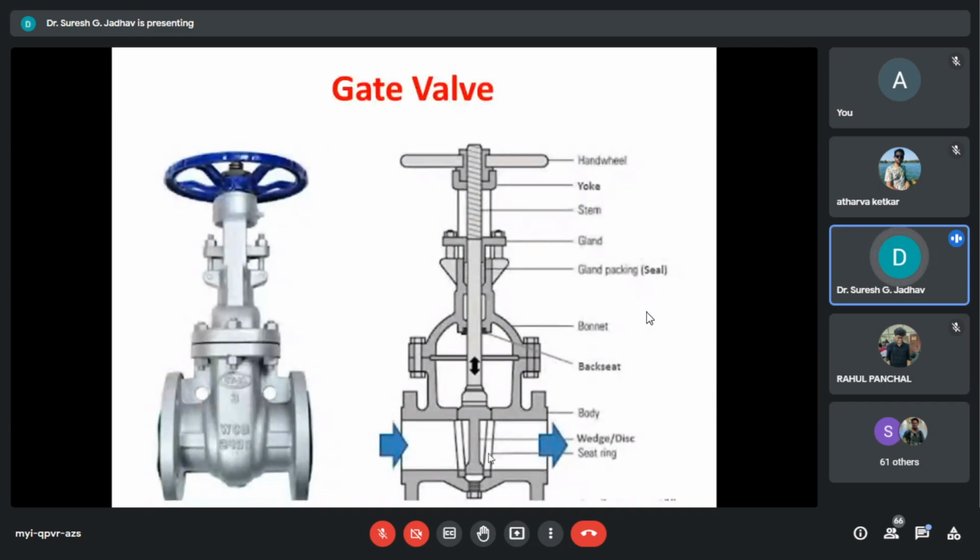In case of low pressure rating, Teflon or Teflon filled for corrosive applications, and for low temperature ratings go for the solid metals, flat metal jacketed asbestos filled, metal ring joints, spiral wound asbestos filled ratings.